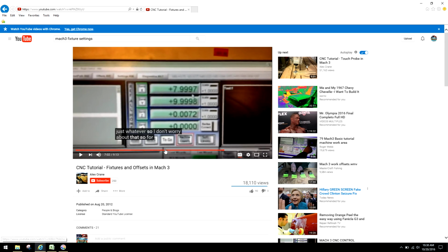Okay. So once again, we can tell this individual is not really familiar with accuracy, because he actually had it programmed in at 8 by 10. You could see here the machine itself is off by a couple 10,000ths of an inch, guys. Okay, so he's 2 10,000ths here, 3 10,000ths there. I mean, for wood routing, that's incredible. That's an incredible amount of accuracy, and that's far exceeding any switch's accuracy.